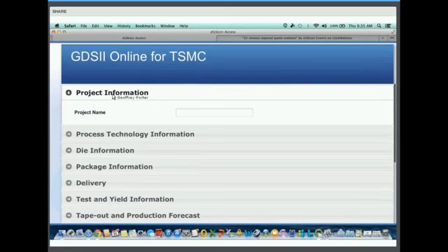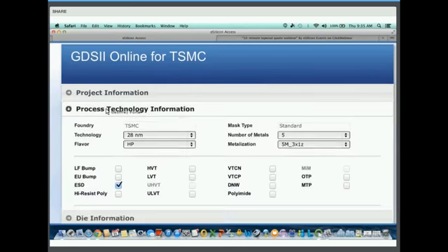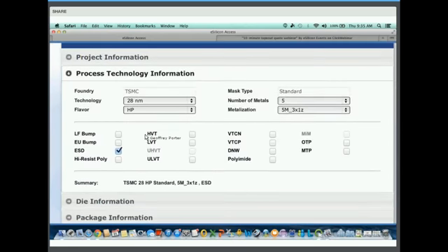So there are some aspects that we've built into this tool to guide and give some advice. One of them, which you can see there, is we're showing what these implants mean. Now Bob, as an experienced manufacturing guy, knew that he wanted the high VT and a low VT to keep power under control and to keep performance up. We're not getting down to that level of detail, but we are explaining what they are to some extent.